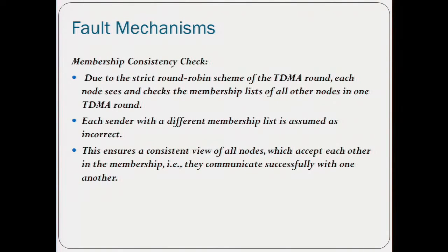So the essential mechanism to have fault tolerance in this TTP architecture is to have an observer that checks either if the slot is empty, so the guy is broken, or if it has data that spills over the slot that is assigned to it. So these are the two mechanisms that can be done.